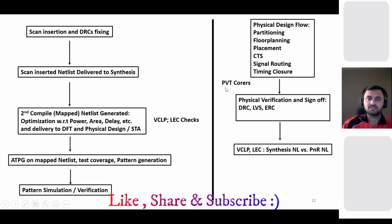And then they will take care of the process, voltage, temperature, the PVT corners, and they will do the physical verification like DRCs. They will check the design rules, and layout versus schematic. Then some electrical rule checking they will also perform. And they will also perform VCLP and LEC between the netlist and PNR. After this placement and route netlist, they will perform this in parallel to the DFT.